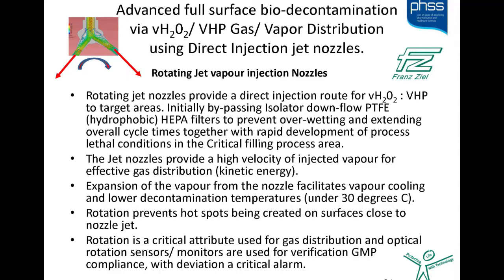As soon as you get into unidirectional airflow, trying to distribute by air, fans, recirculating, where it speeds up across the floor to the return air ducts, that's where your risk of positive BIs is, because fast airflow across a surface doesn't help the molecule exchange on the surface.